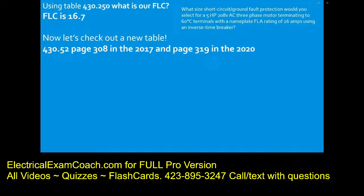So let's go ahead and answer our question. First, we find our motor in the motor column. We go down to polyphase. I want to let you know that that just means 3-phase. Now we come over and tee off with our type of device. In this question, it was an inverse time breaker.